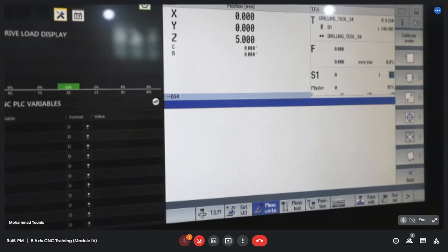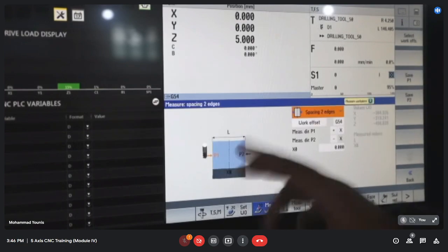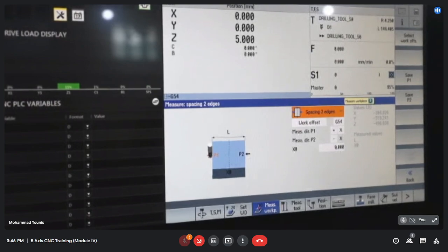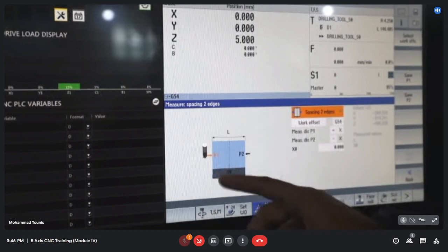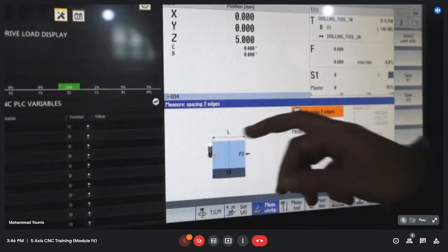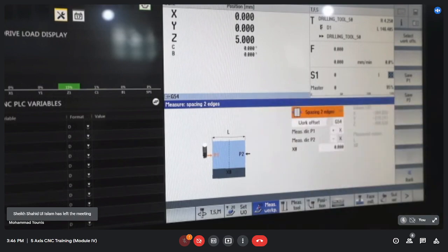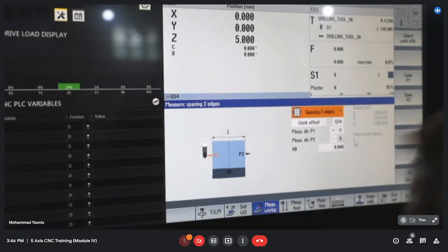First I will do one more cycle on work offsetting. I'll now be setting the work offset at the center of the workpiece. Okay. I will set the origin point at the center now. For that, I need to touch the probe on the two sides in the x-axis direction, and I need to follow the same procedure for the y-axis. And for the z-axis, we just need to touch it on the top surface. So we'll also perform this cycle. Then we'll move forward.